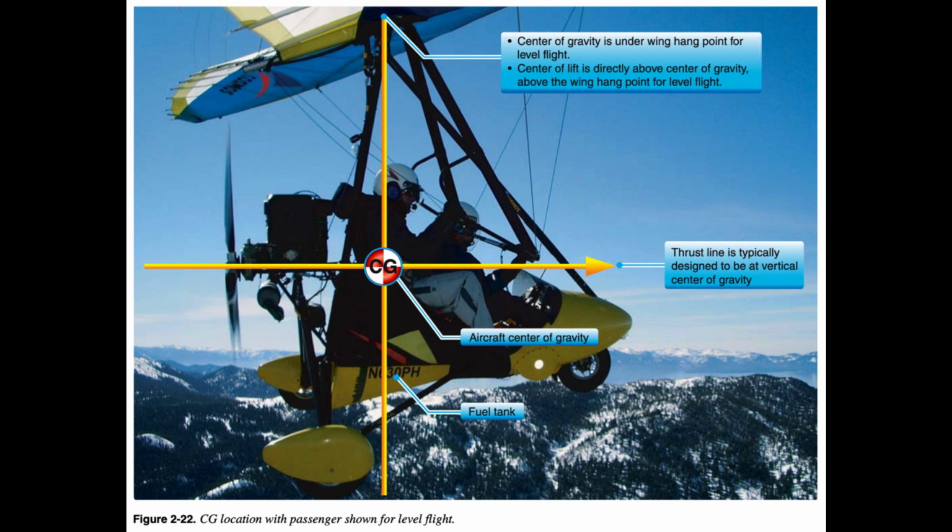Center of gravity, CG. The CG is the theoretical point of concentrated weight of the aircraft. It is the point within the WSC aircraft about which all the moments trying to rotate it during flight are balanced. The most obvious difference in the CG for a WSC aircraft is the vertical position compared to an airplane, as it is always lower than the wing. The Pilot's Handbook of Aeronautical Knowledge accurately states the CG is generally in the vertical center of the fuselage. The same is true for the WSC aircraft.